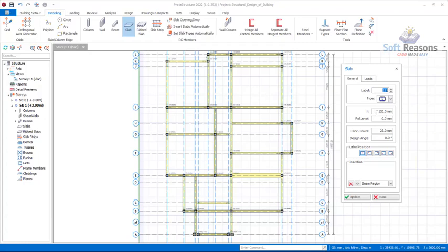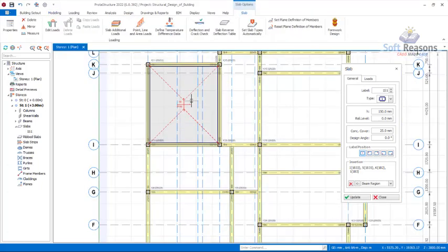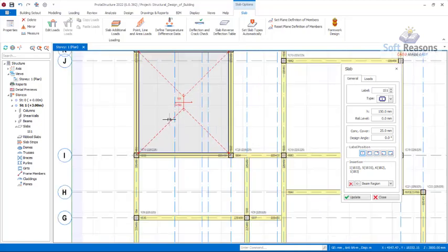So here is the level of the slab. The slab thickness is going to be 150 millimeters, a solid slab we are using in this structure. We have the concrete cover right here to be 25 millimeters. We'll go by that. The extraction points is going to be beam region. We have various extraction points here; it all depends on where you should have that done. So we use beam region right here, placed by clicking in the provision bounded by the beam to be able to insert the reinforced concrete slab just like this. The load on it, we have not actually gotten done.